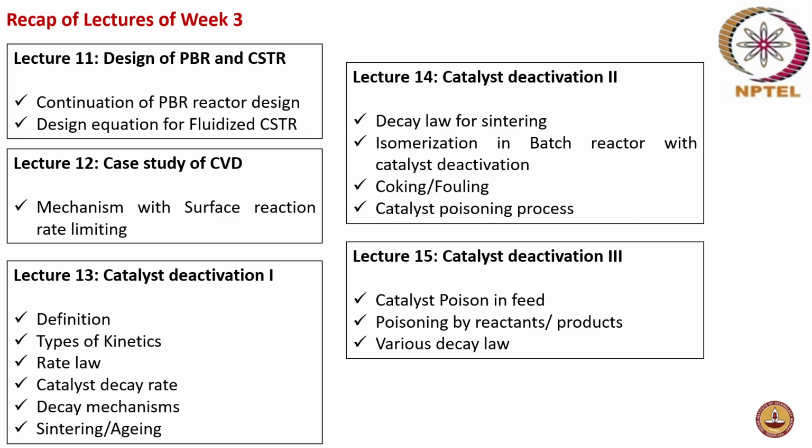What happens when there is coking and fouling or a catalytic poisoning process were all discussed among catalyst deactivation. And what if catalyst poison is there in the feed, and if the poisoning is by the reactant or product itself, and what are the various decay laws were all discussed in week 3.